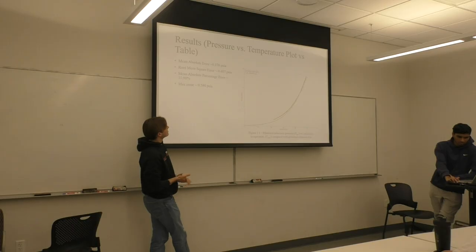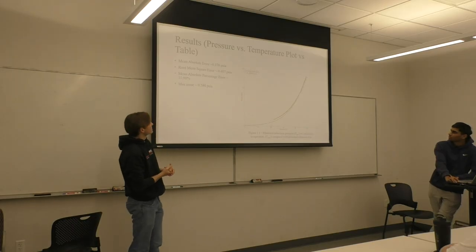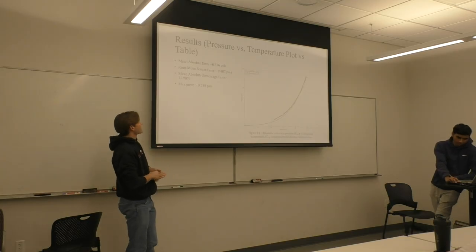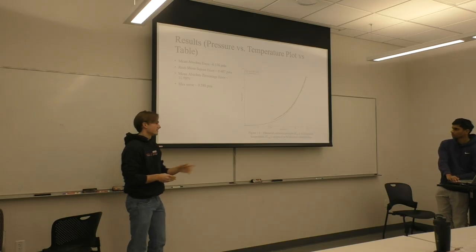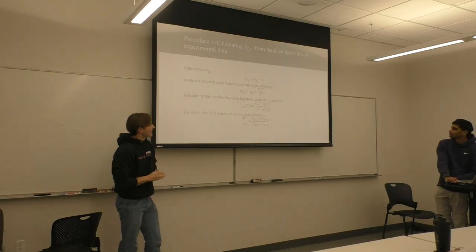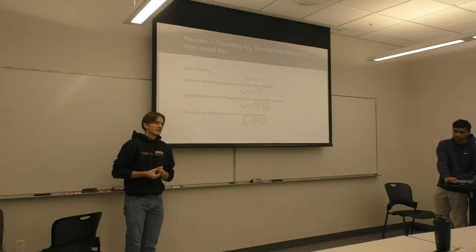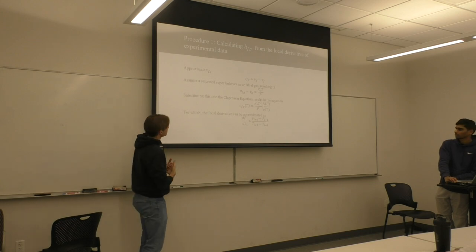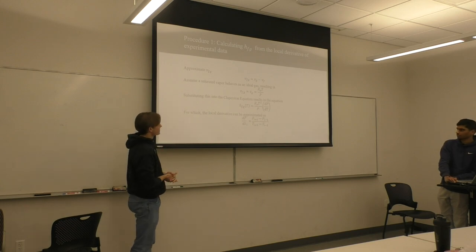Next page, please. So if you plot the saturation pressure and temperature that you get, you can see that it actually matches the tabulated values very well with a max error of about half a PSI. Next slide, please. And so actually taking this and calculating the enthalpy, which is what we wanted, we need to rearrange all this data in this form here.